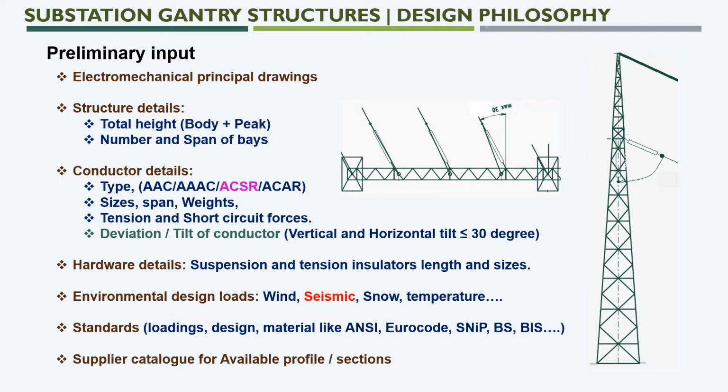Next input we require is hardware details, that is suspension and tension insulators. In that we need the length, size and weight. Then environmental design loads such as wind, seismic, snow and temperature. Generally we can ignore seismic by comparing it with wind in most projects, but some customers ask us to calculate both seismic and wind loads in separate load combinations. If it is requested by the owner of the project, we obviously need to do it, or else we just compare the wind and seismic impact.